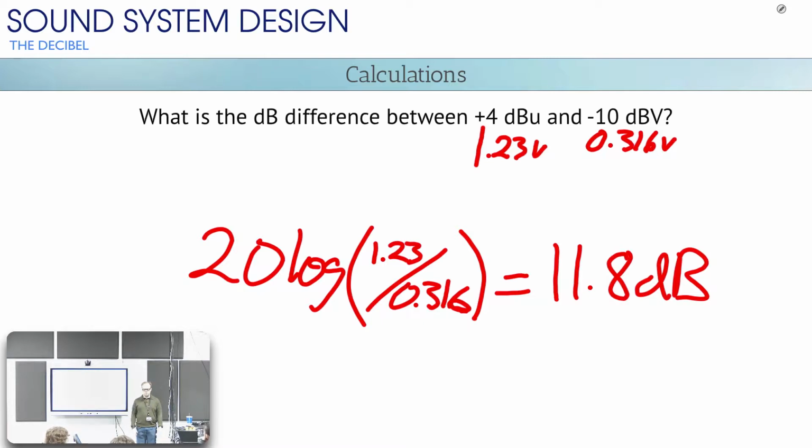No, I mean, just on your mixing console. What sort of things can you turn knobs and push buttons on mixing consoles to fix stuff like this? I would just turn the gain up 12 dB on the channel that has the consumer level input into it. That's what that knob is for. That's what the gain knob is for, to line up input levels, to get them all maximized for your